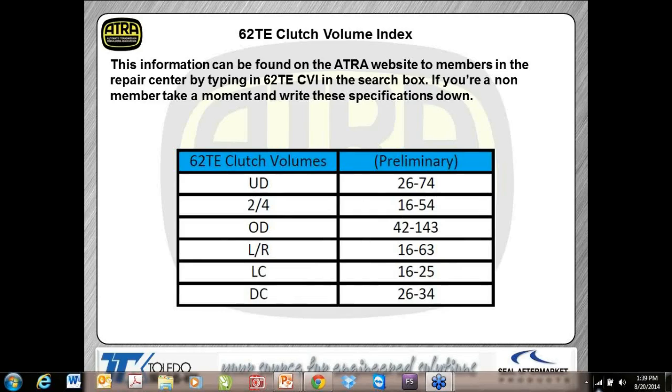Now, what I did find out the other day was, that it's not in your handout, but you can do another print screenshot of this slide if you'd like. Sometime during the mid to late 2013 model year, last year, the OE came out with a new low clutch drum. And what it has is anti-rotating rings similar to what you would find on a 4T65, which to me makes quite a bit of sense.